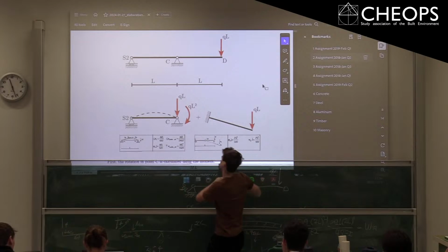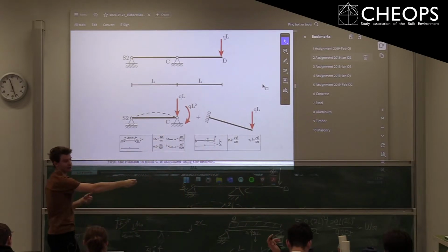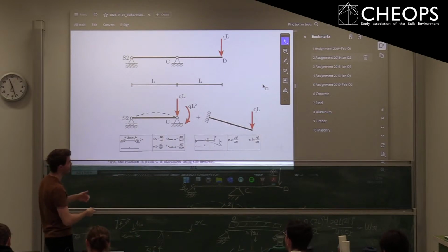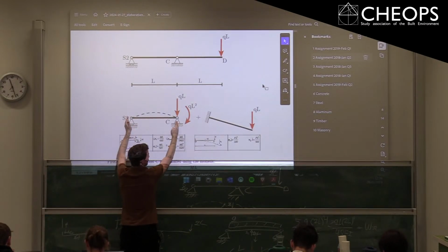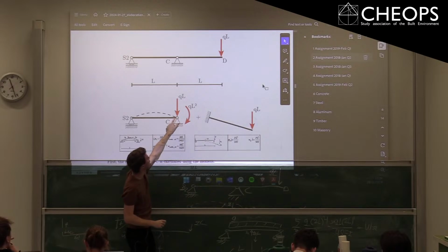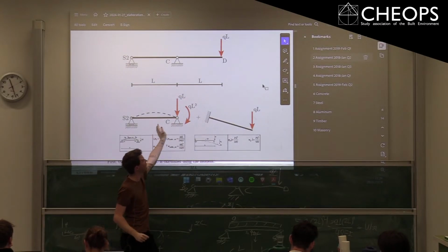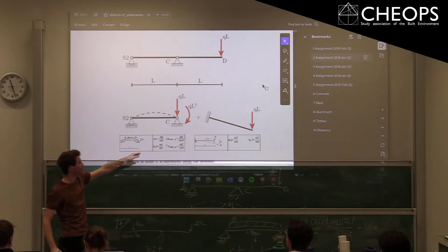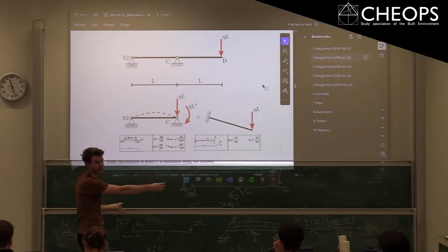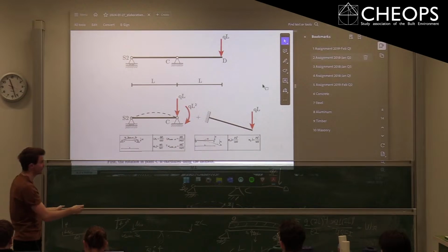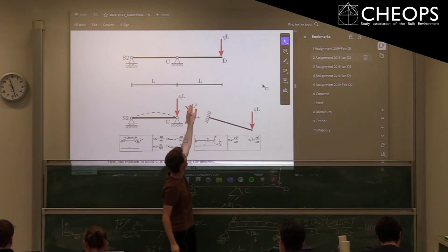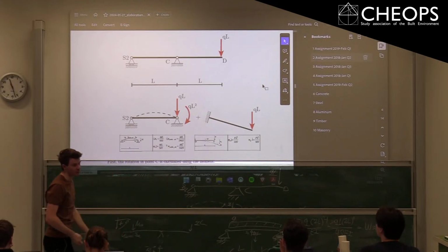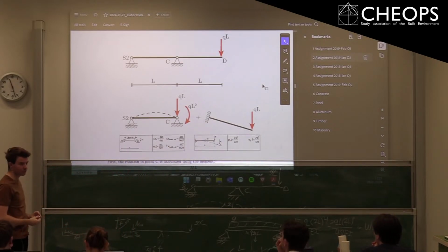But if you're looking in point C, that force is a distance away from you, right? And then we are working with the definition of a bending moment. So if I'm only considering this part, these two forces are basically representing anything that's going on that side of that point. So what's going on C to D. So both the vertical load plus that distance times your force. But this is simply that second part. So exactly, and there is no moment. Yeah. Okay.